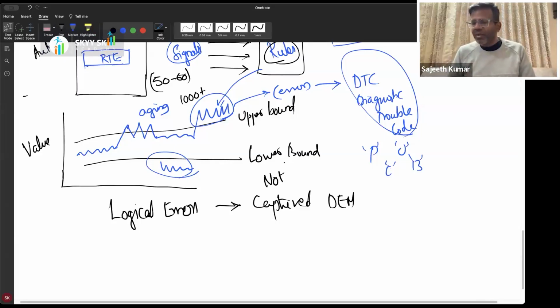There are definitely things possible like that. Let's take, for example, you're monitoring the motor's voltage alone. And let's say that the bearing in the motor has become weak. So now the motor will start making some noise, and there's going to be reduced performance. But if you go and check your error codes, there might not be any errors which have popped up.